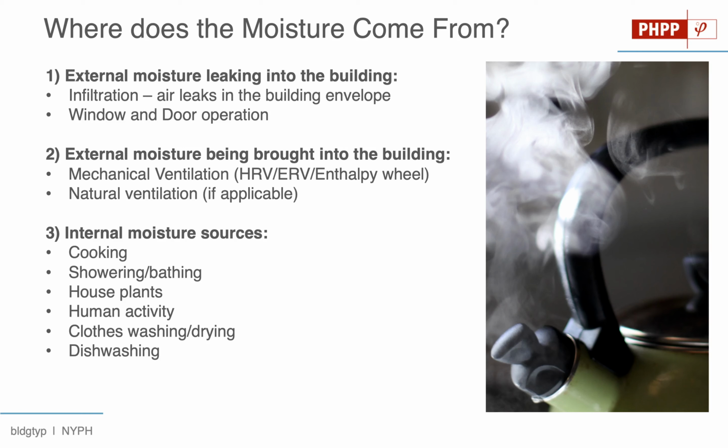Now, of course, we also have a bunch of intentional air exchange. We have a machine, an HRV, an ERV, some sort of ventilator with some fans, which is taking outdoor air and bringing it right into our building. And it's going to be doing that all summer long. It's going to be doing that because people have a nasty habit of doing things like breathing all summer long. And so that ventilator machine is going to be operating all summer long, and riding on that ventilation airflow will be a bunch of moisture.